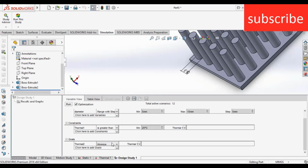So basically what I want is for my temperature to be minimized at the tip. For that I am choosing minimize. If you want the temperature at the tip to be maximized, just click on maximize. Remember, it is up to you how to do the simulation. After doing all this, click on run.